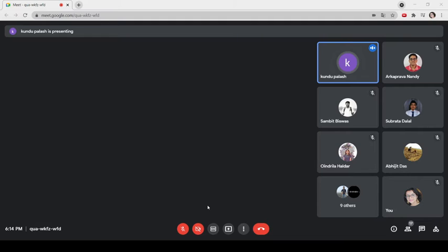Then for mode 3, split timer mode. Split timer mode is a very advanced feature. That means the 16-bit timer can be divided into two parts, which can be operated simultaneously, each with its own basic clock frequency. Now the question will arise whether the timer clock frequency under split timer mode is derived from the same clock source. Even though the timers are operated in split timer mode, that is under mode 3, the basic timing signal, that is the clock rate, may be different. But here the clock rate will be the same.